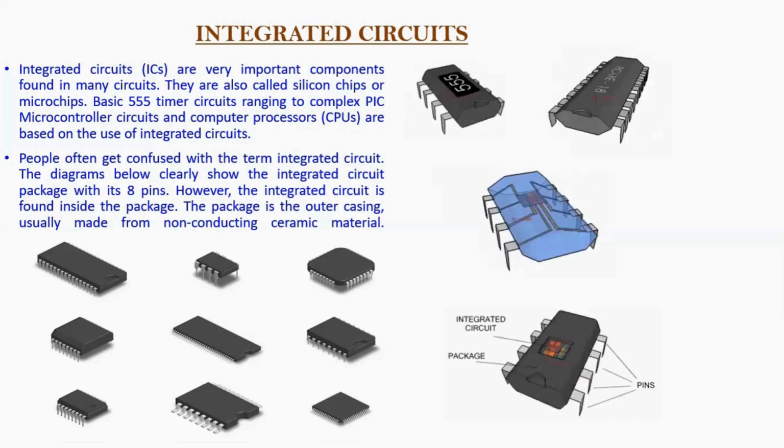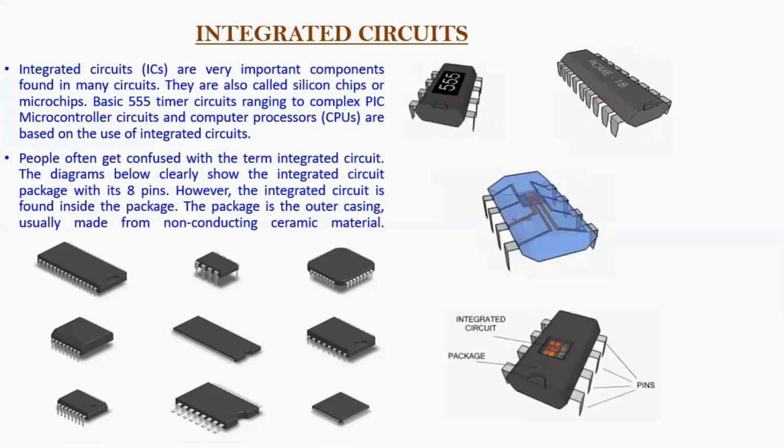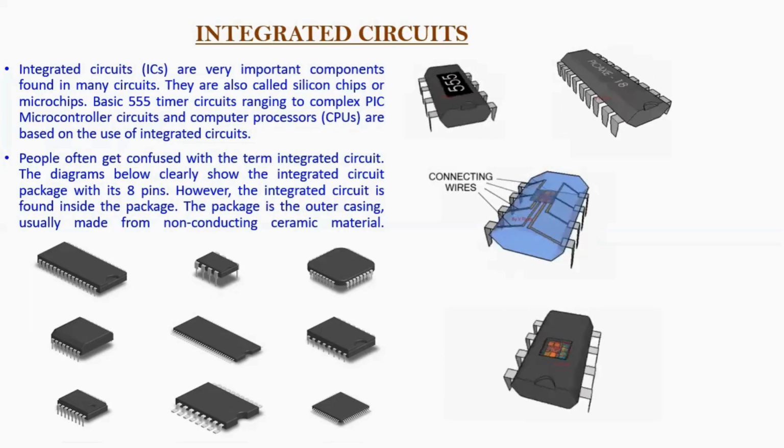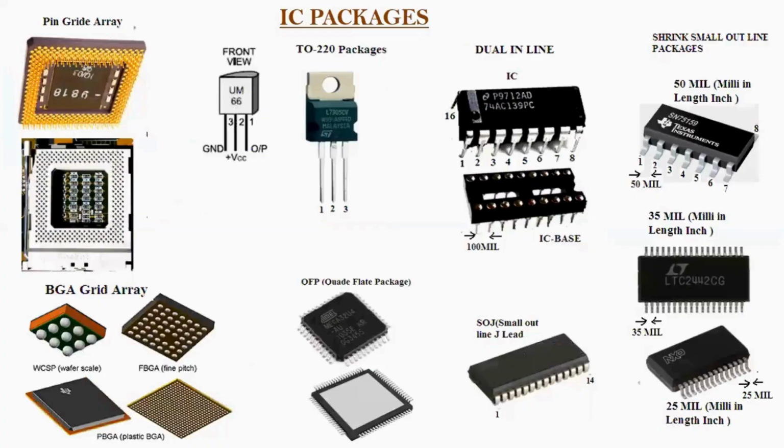A little explanation I've given you about ICs. It will have a different number of pins. There will be a notch, and on the left hand side of the notch, going anti-clockwise, you have to count the pins. Okay, now we'll go to the next one.